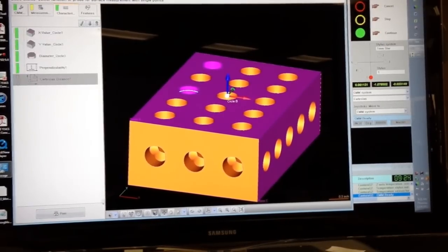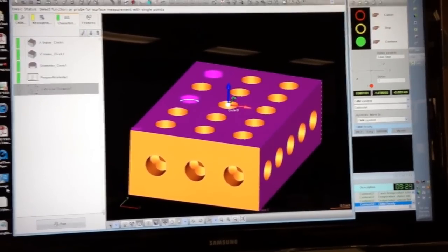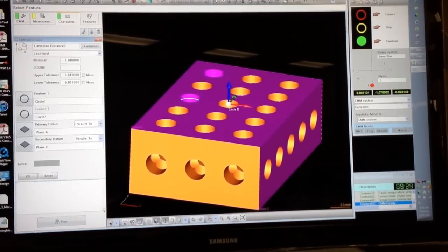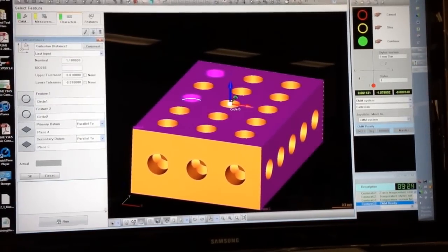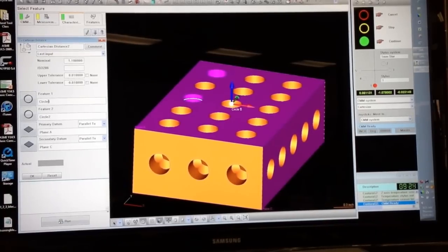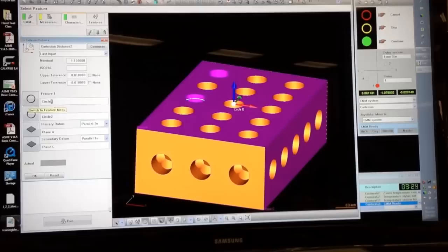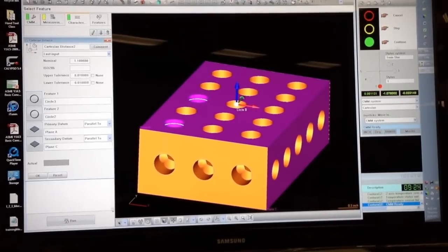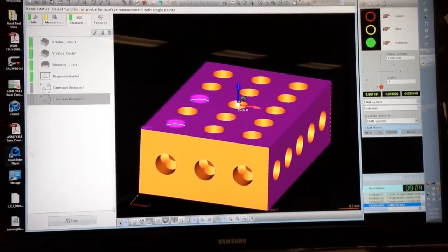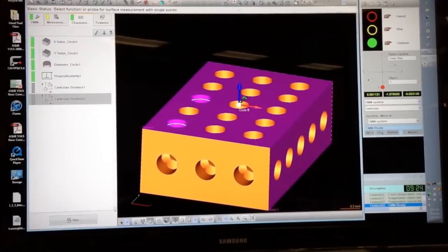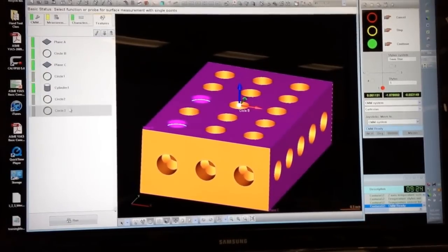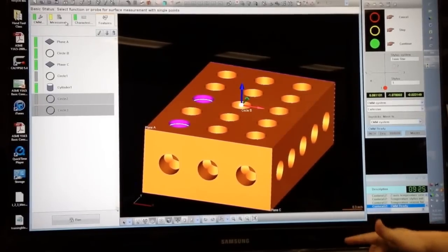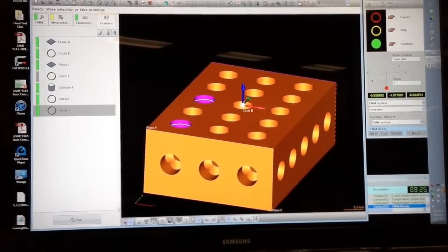I'm going to take my first Cartesian distance, Control-C copy, Control-V paste, and now I'm going to open up the pasted copy. I have distance from circle 1 to circle 2, and now I need the distance from 2 to 3. I simply highlight where it says 1, type 3, and enter, and now I have the distance between 2 and 3. So quickly, I've created both of the characteristics I'm looking for, and once again, I can come back here, Shift, F9, and execute and test both features.